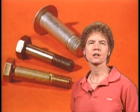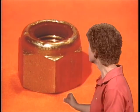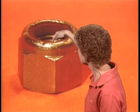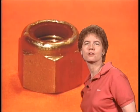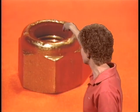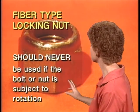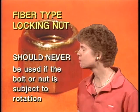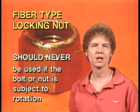Now, let's take a look at a fiber type lock nut. When you have a fiber type lock nut, the locking feature of it is obtained by using an unthreaded fiber locking insert. So inside the nut there is a fiber insert, and it is not threaded, so when the bolt goes into it, it tightens up, and that provides the lock nut feature. The fiber type locking nut should never be used on an aircraft if either the bolt or the nut is subject to rotation, because it won't hold the way you want it to. Never use it if either the bolt or the nut is subject to rotation.